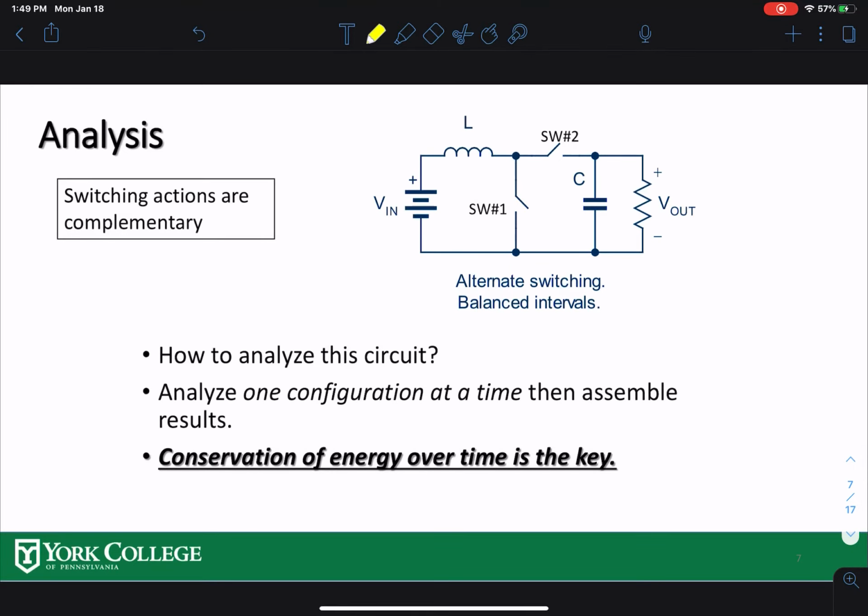So how to solve it? The only way you can solve it is called conservation of energy. That means we're going to take the energy storage device, and make sure that we are using energy conservation theory across the device, and you're going to go from there. For example, if we use an inductor as your energy storage device, and we apply the energy conservation law, an ideal inductor should not have any energy stored into it after a period. Whatever energy is stored should be released in the next cycle. So there is no net energy storage in the inductor over a period.